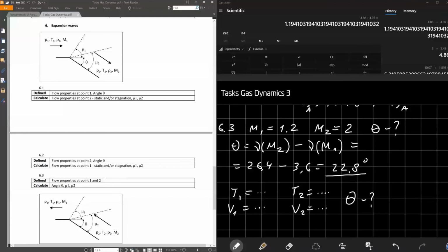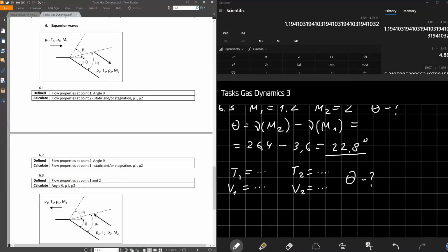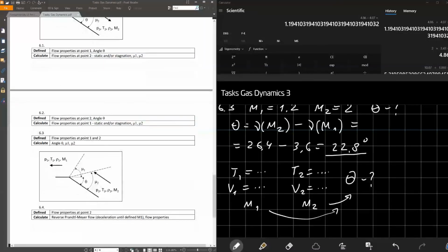And in this case, what you do, I think you already understood. From these two parameters, you calculate Mach 1. From these two parameters, you calculate Mach 2. And applying directly the formula of the Prandtl-Meyer function, you calculate the theta angle of the body. That's simple. Nothing complicated. Calculate speed of sound, calculate Mach number, and calculate theta. Just very simple operations, I hope.